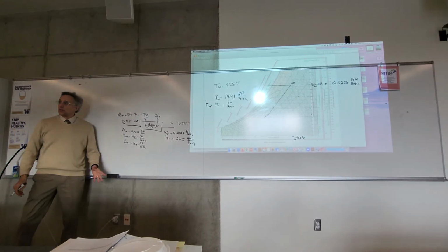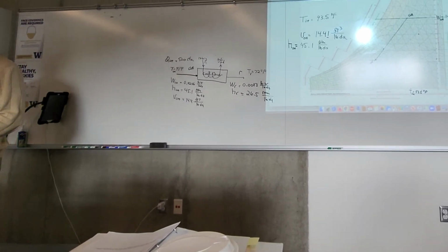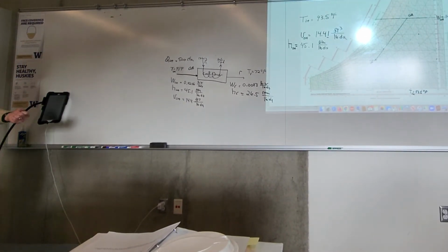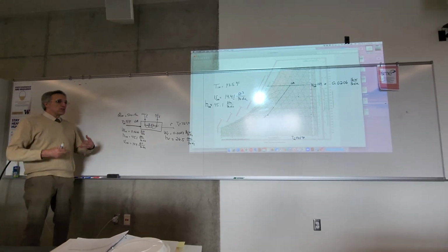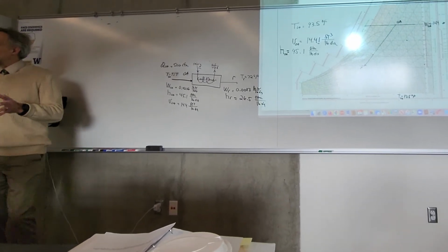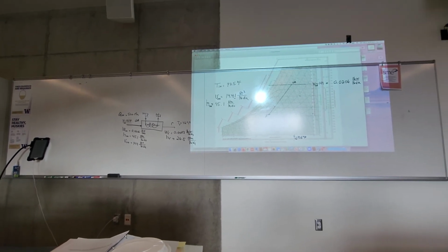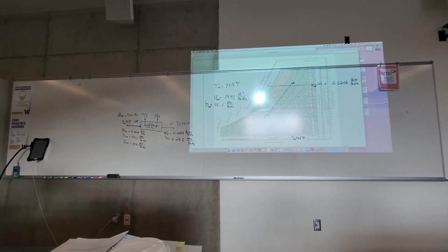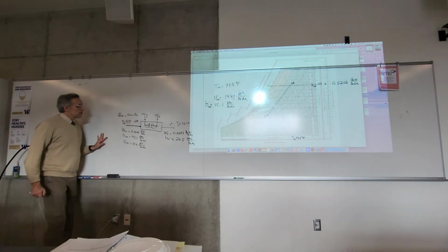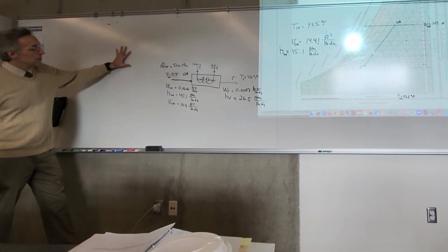Those are becoming increasingly popular because you use those for humidity control. The state of the art now is to separate humidity control from temperature control. We have two separate systems. One system controls the dry bulb temperature, and a separate system does the humidity control. That seems to be more energy efficient than a DOAS system, and is a good humidity control.